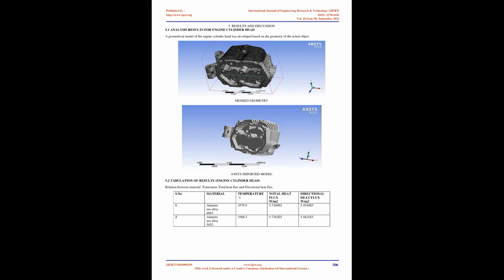The valve overlaps have been removed and the additional 2 strokes have been provided for better scavenging, using air injection. The engine shows 40% reduction in fuel consumption and dramatic reduction in pollution. Its specific power is not less than that of a 4-stroke petrol engine. The engine can run on a variety of fuels, ranging from petrol and diesel to LPG. An altered engine shows a 65% reduction in CO pollution when compared with the 4-stroke engine from which it was developed. Modification in 6-stroke engine.